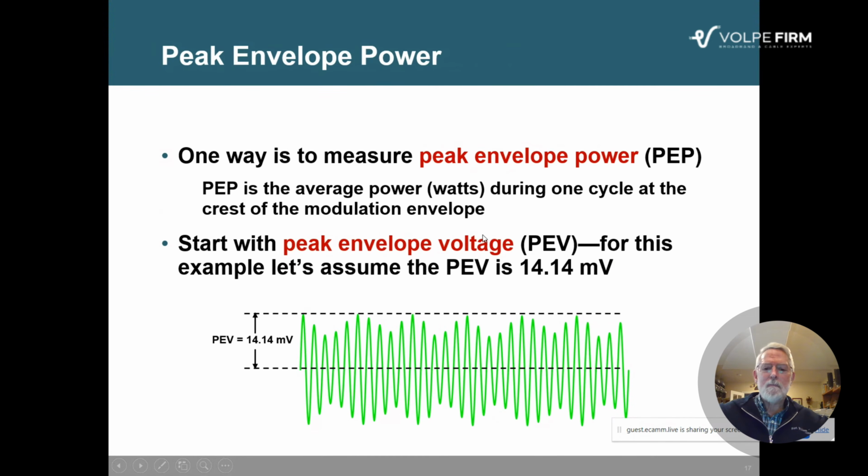When we talk about root mean square and average power, it almost seems like they should be roughly the same thing when we're looking at something like this. Are they, or are they different? The formula for power is root mean square voltage times root mean square current, and that gives us average power. Well, that's kind of complicated, Ron.